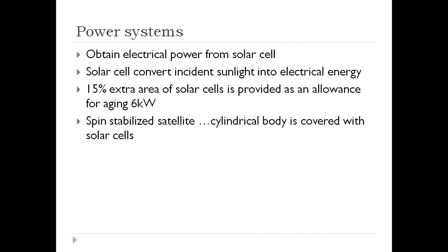A primary advantage, however, is that by unfurling a folded solar array when the satellite reaches geostationary orbit, power in excess of 10 kW can be generated with large arrays. To obtain 10 kW from the spinner requires a very large body on which to place the solar cells, which may then exceed a maximum payload dimension of a launch vehicle.